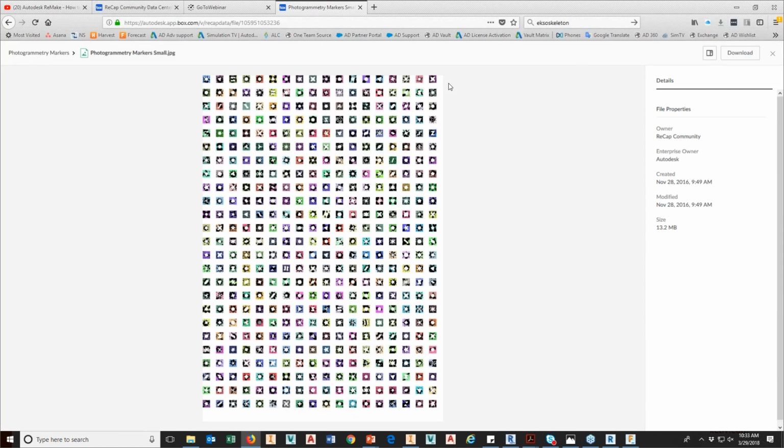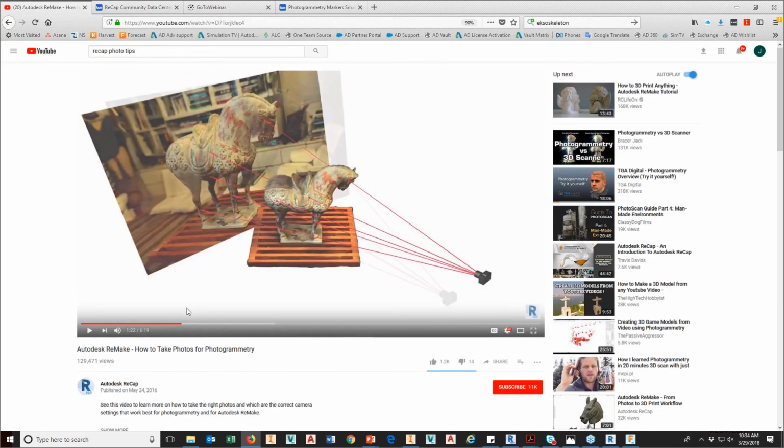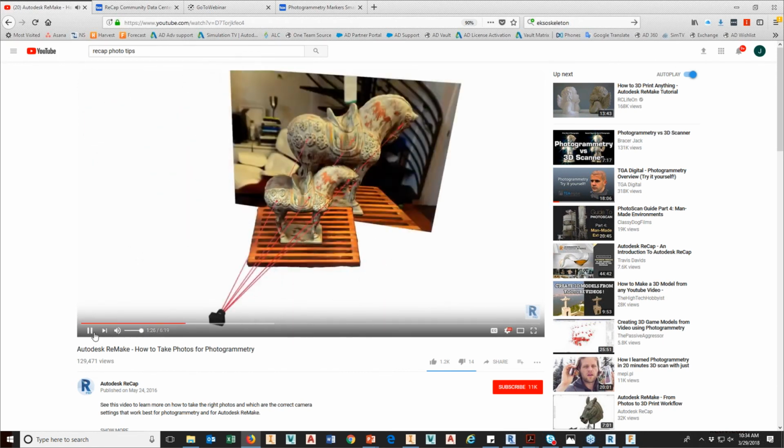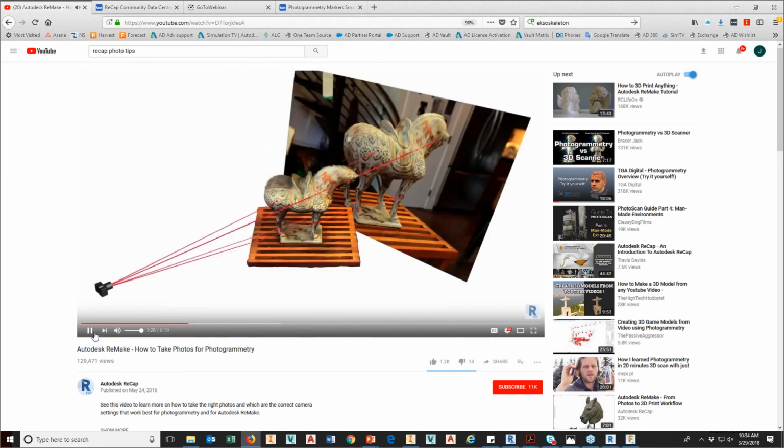Another thing that I've seen people do is they put Post-its and markers and stuff. If you see people laser scan in general, like facilities, they put stickers everywhere. Those stickers make it really easy to stitch the scans together. Usually they're super contrasty compared to the actual product or facility that you're scanning. You want that so that when the program starts stitching it all together, it understands, hey, this bright orange dot is this bright orange dot everywhere.